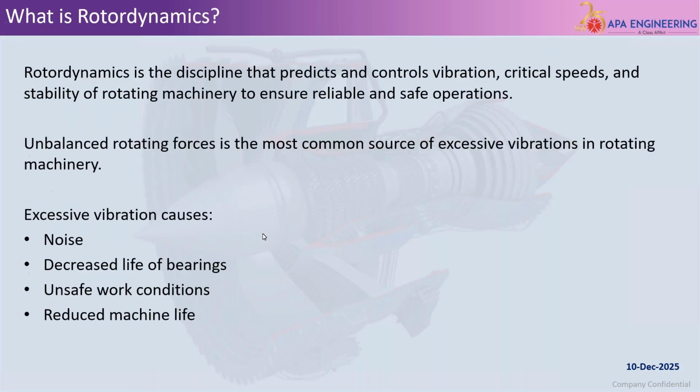First of all, let's understand what rotordynamics is. Rotordynamics is the discipline that deals with predicting and controlling vibration, critical speed, and stability of rotating machinery. This is extremely important because rotating equipment like turbines, compressors, pumps, and motors typically operate at very high speeds, and even small imbalance can cause large vibration issues.